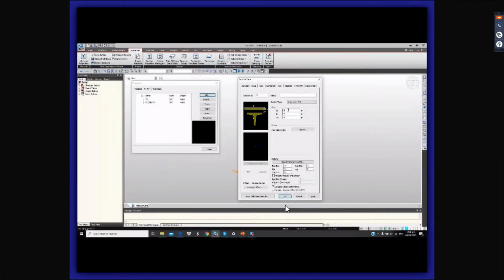So for B, we need to define the slab width, then the thickness of the slab should be 0.18, so 180 mm. It is also stated in AS 5100 regarding the slab thickness and the slab width. Then we will be importing the PSC sections that we have defined.